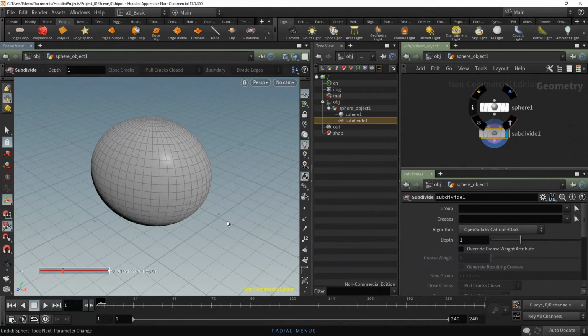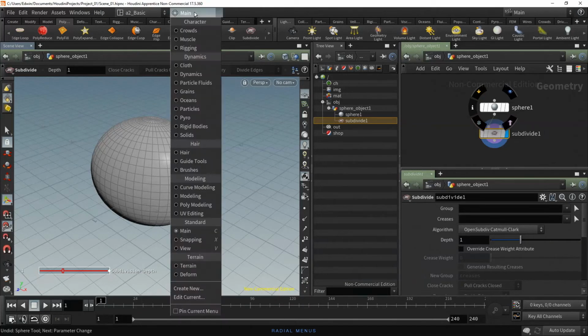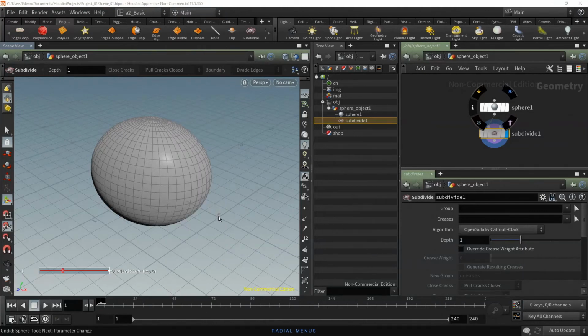You can choose what tools are shown in this menu using the Radial drop-down menu located in the menu bar. Here you can select a preset according to the required task. Finally, the V key to access the view controls: selection options, selection tools, shading display, and viewport layout.